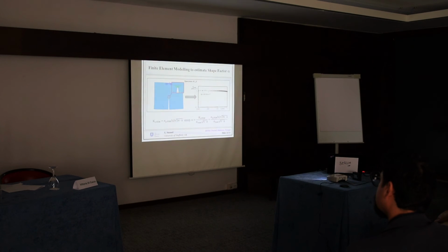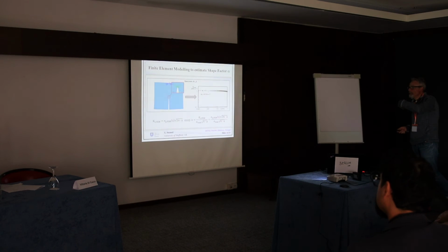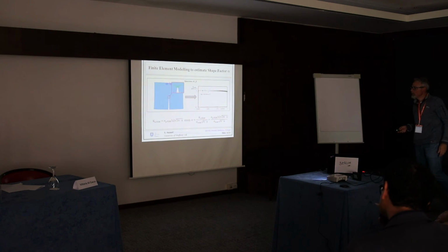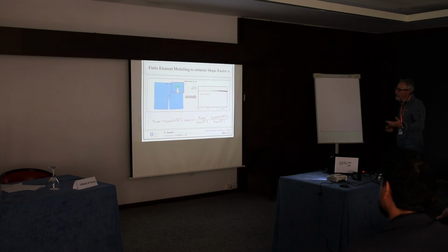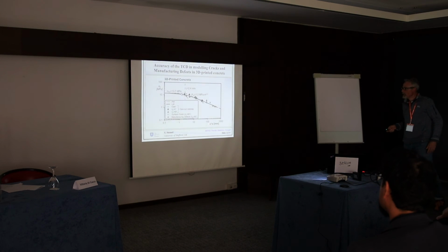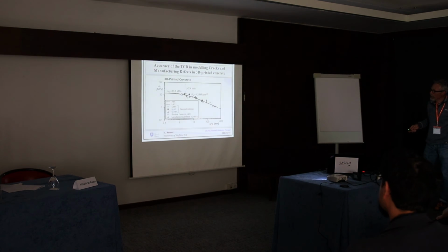So what we did, having those definitions, we could apply the usual procedure we use to calculate the shape factor for the various geometries. So we had the shape factor for the various geometries, considering the equivalent cracks. And we used that shape factor together with the definition for the crack depth I showed you in the previous slide, to build up this kind of representation.